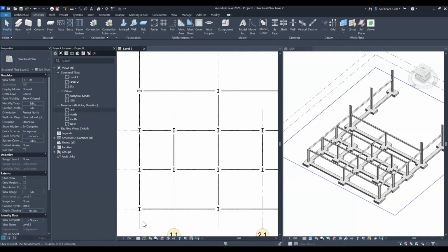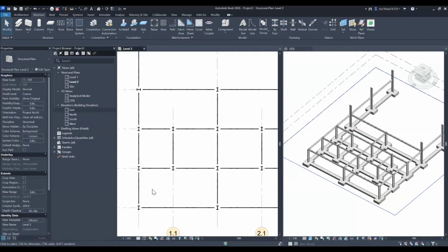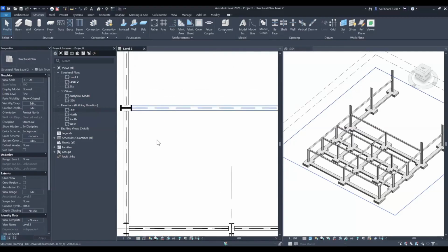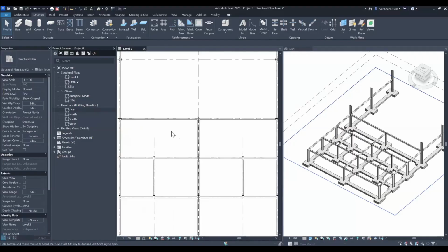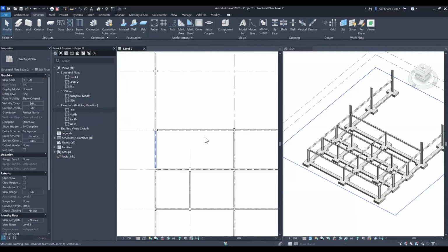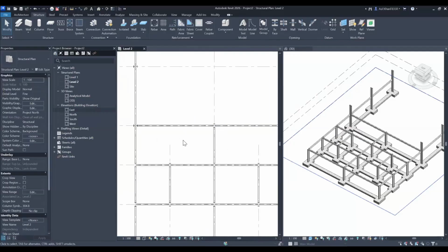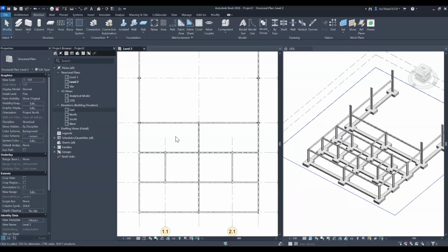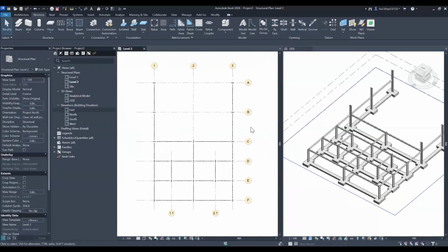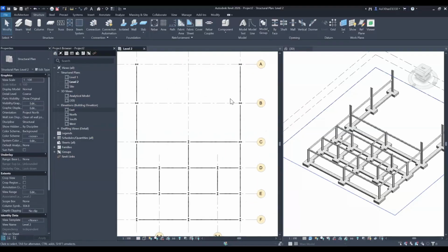So one of the greatest benefits of using Revit is that you can change your level of detail. For example, it's now coarse. If you change to fine level of detail, it will show you the exact size of the beam. I haven't done any line work yet, no extra work, no offsetting, trimming, no movement, no rotation, and everything is done pretty much automatically. And this is the industry standard presentation we usually do when we work in framing layout.